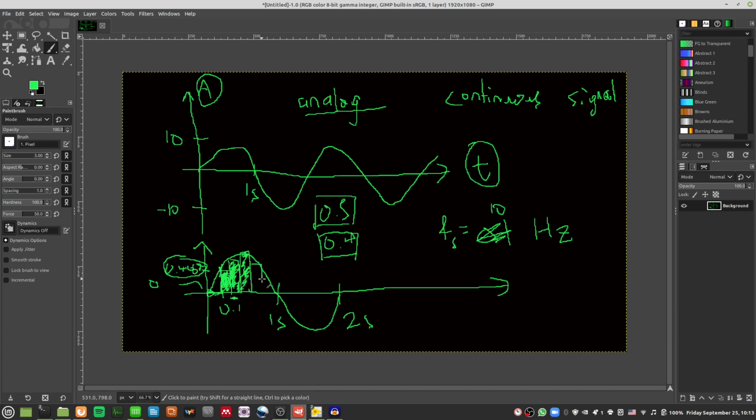So after a while, you will have something that approximates the waveform that you see. You'll have sort of a bar chart that samples the waveform that you see here. This is what sampling rate is about, and that helps to convert from an analog signal to something more like a digital signal.